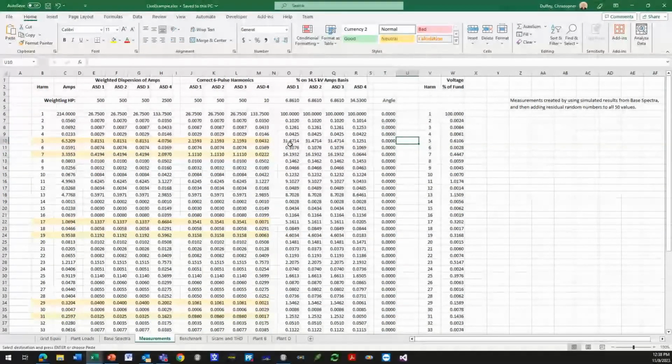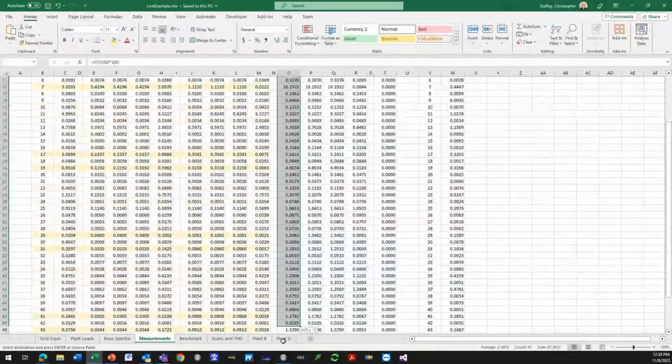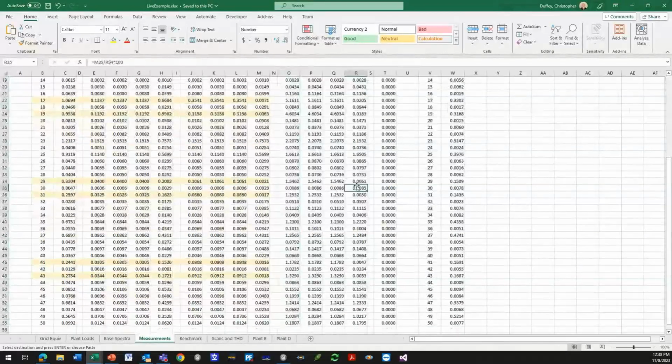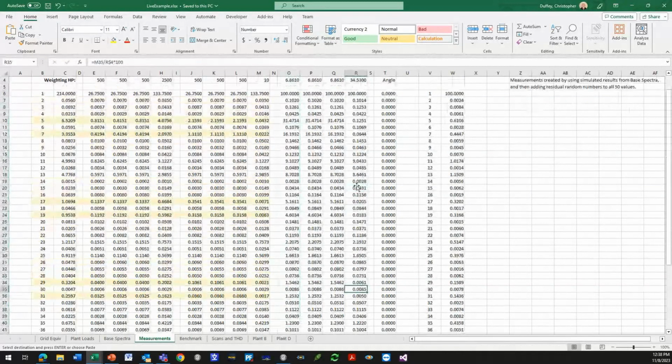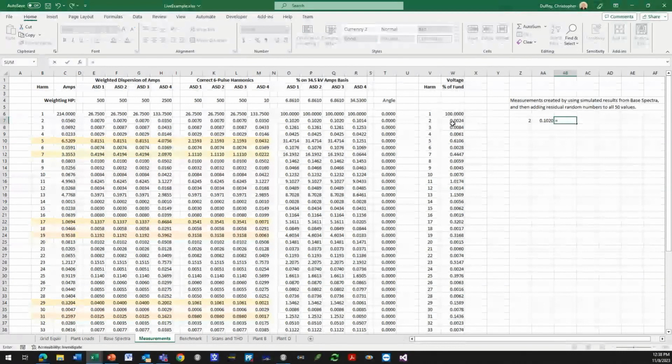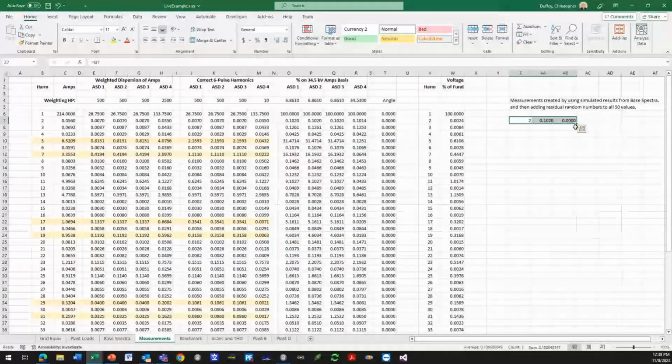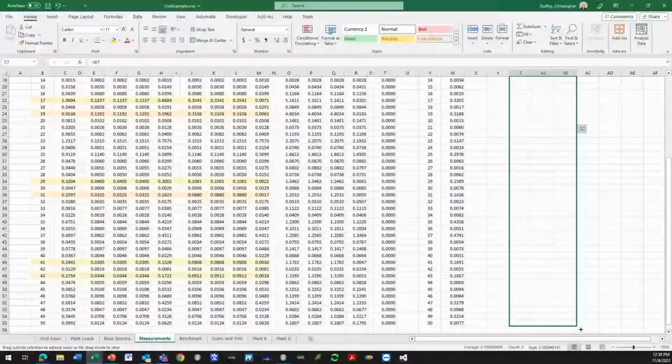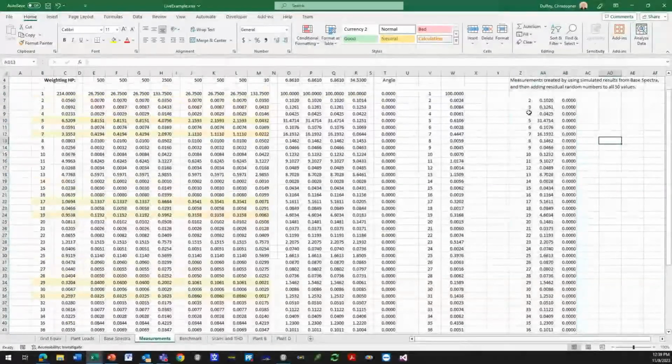So I'm going to take this column. Excuse me, I have to come over here and I need harmonic numbers. So the best way to do this, to make it really quick, is I would say equals this. I would put the spectral content here because it's going to be 3 columns in Easy Power, and I'll say this equals here. And then here I would say equals the angle 0. And now I have 3 columns all set with the information that I want.